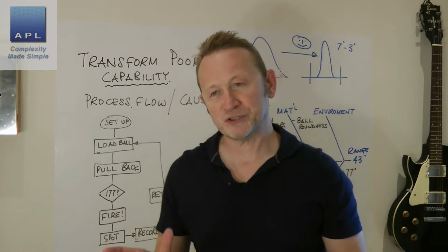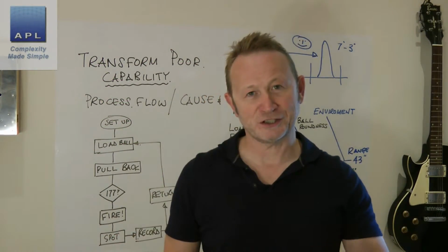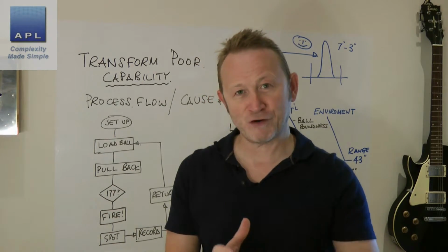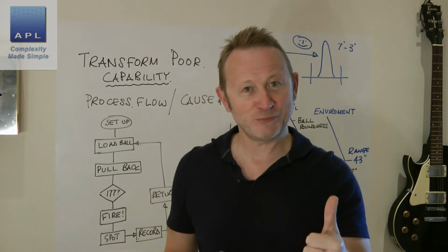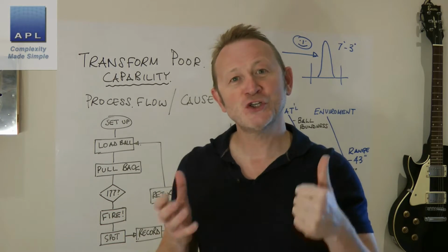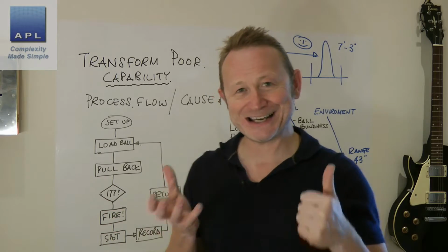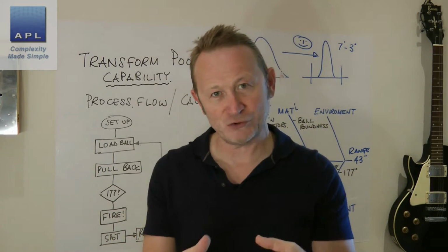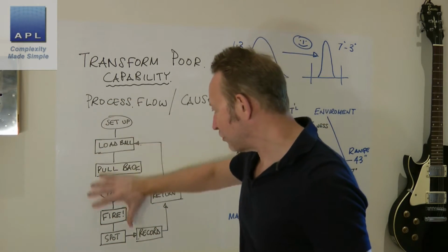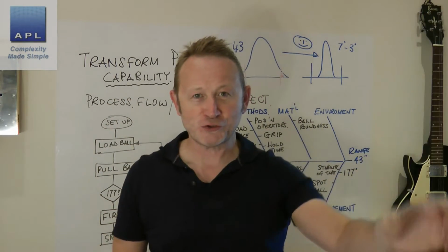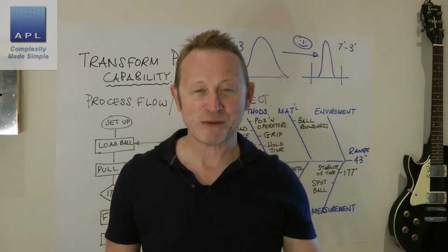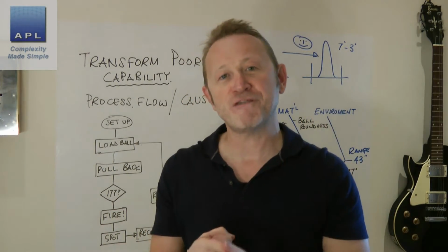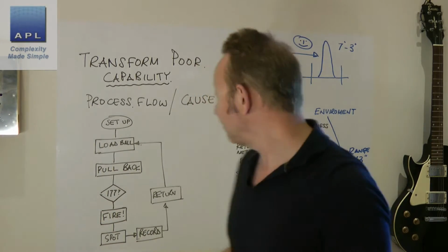And just one last point to make about this technique. This technique feeds directly from your FMEA processes when you do new product introduction. This is the exact same technique that the FMEA is trying to get you to do. What does it ask you to do? It asks you to put a flow diagram, the process step, on the left hand side of the form. It asks you to identify the failure mode. What's a failure mode?